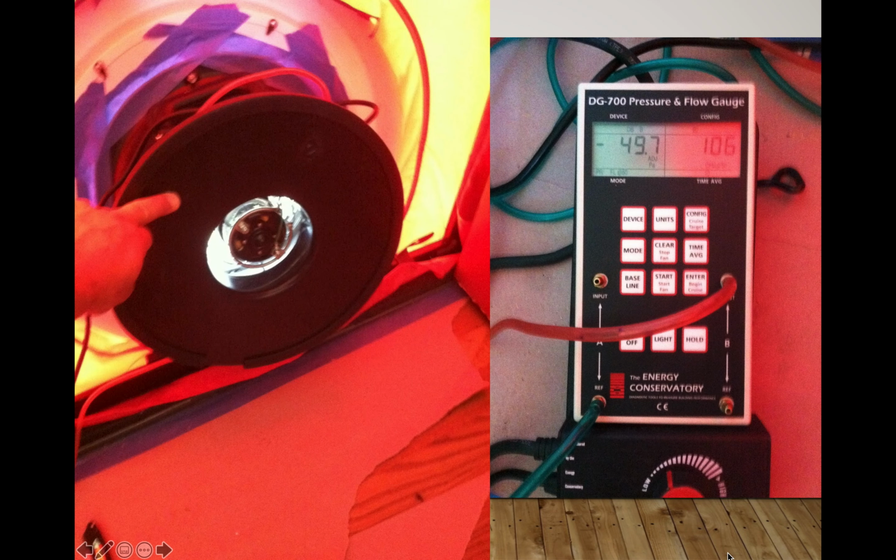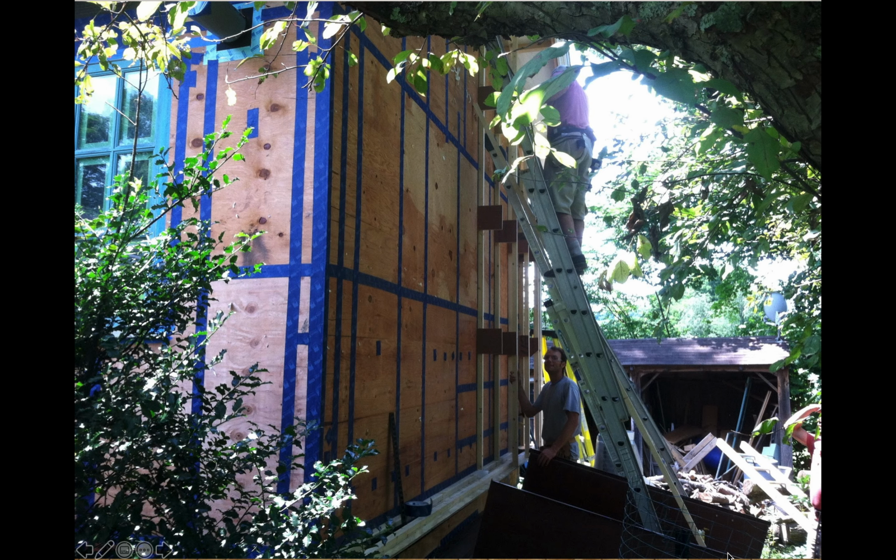But the key thing was to achieve an extreme air tightness, and so I used a version of a blower door that I discussed earlier to get the building extremely airtight. And we're going to talk about how to measure airtightness and what's extremely airtight and what's not, and how to compare that to other standards. And the key tool we used was tape.